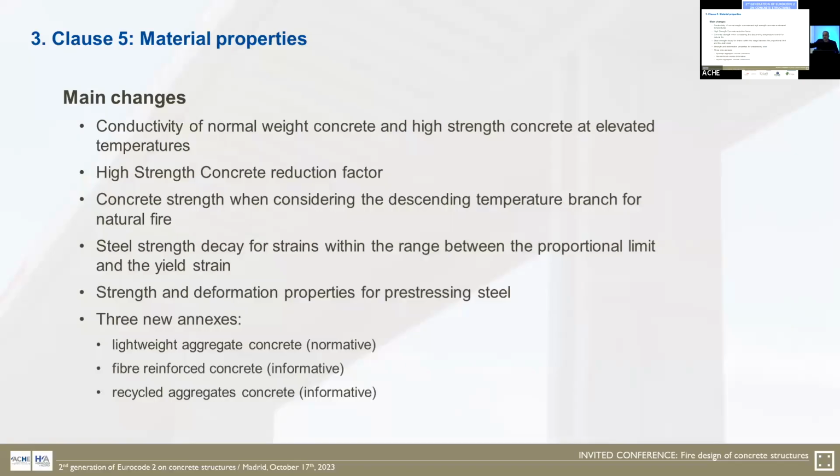What happens when you cool concrete down? Does it recover? Doesn't it recover? So we try to answer this. And then there are some additional provisions and some simplifications regarding steel strength decay and the strength and deformation properties for pre-stressing steel. We also have 3 new annexes, one of which is normative, and it deals with lightweight aggregate